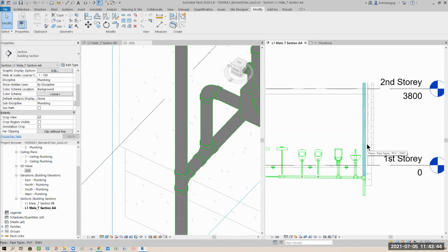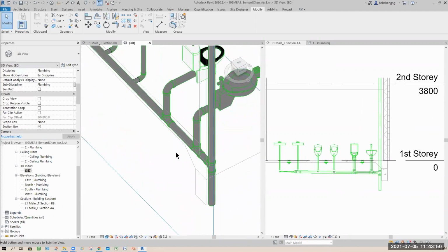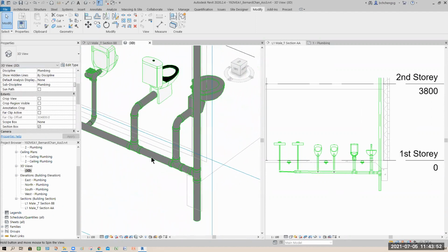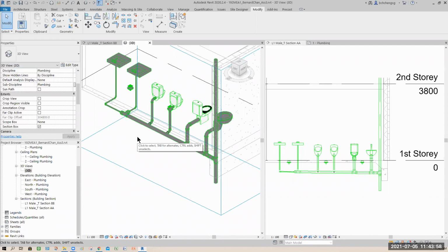Okay, all good. So to ensure that your two WCs are temporarily connected this way. If you are doing the ladies toilet, your first two are connected, but your third one you must connect to this pipe. Always remember, if it's not connected to this pipe, you must at least pipe somewhere and connect back to here. These are things that you need to be aware of. Maximum only two connected. Maximum.